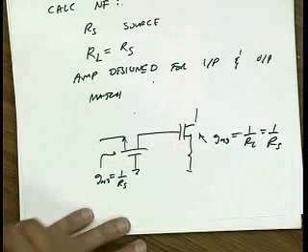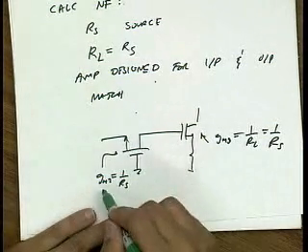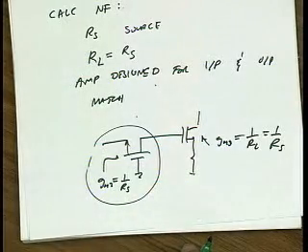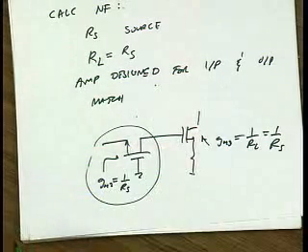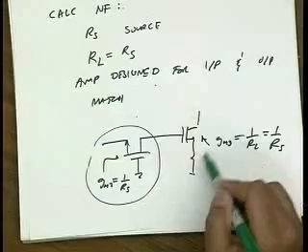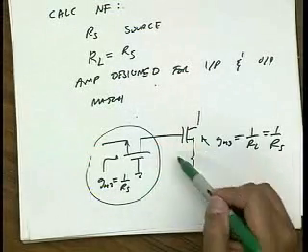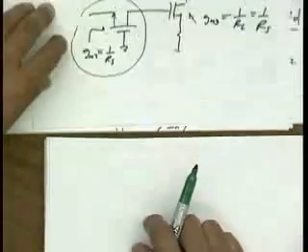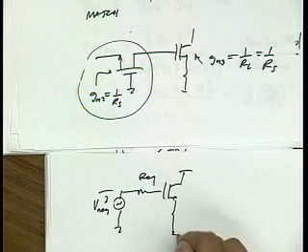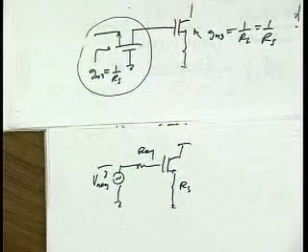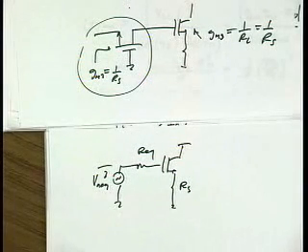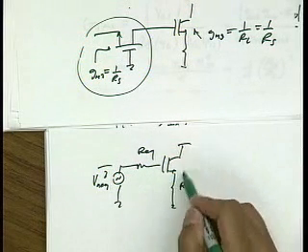Okay? Now, the situation for the students last year was slightly different because they had a problem where they had to calculate the noise of a common gate amplifier. Okay? So those students, again, this is a test. You don't have that much time. It's probably not good to do detailed calculations. So what I was hoping students would do is basically take the noise of a common gate and cascade it with the noise of a follower. So the expectation I had was that they would replace this problem with an equivalent problem, V noise equivalent just driving a common source loaded with RS. So all they had to do was really find the additional noise added by the second transistor, and they could add it to the noise of the overall to get the total noise. Okay. So really the problem narrowed down to finding the noise of a follower.